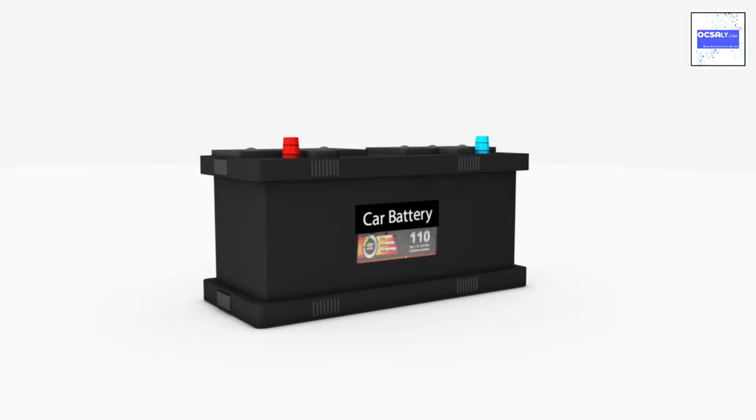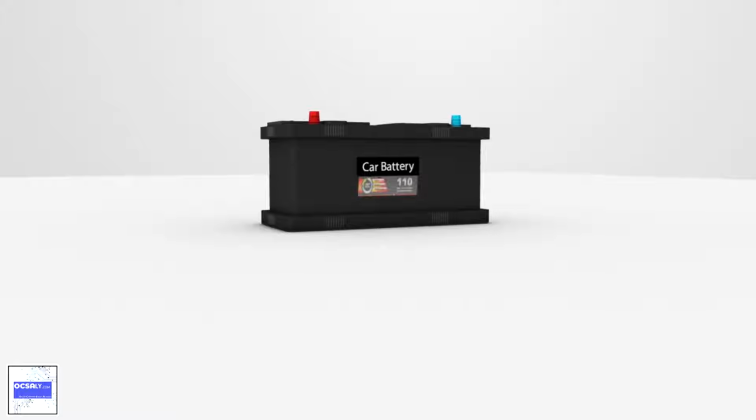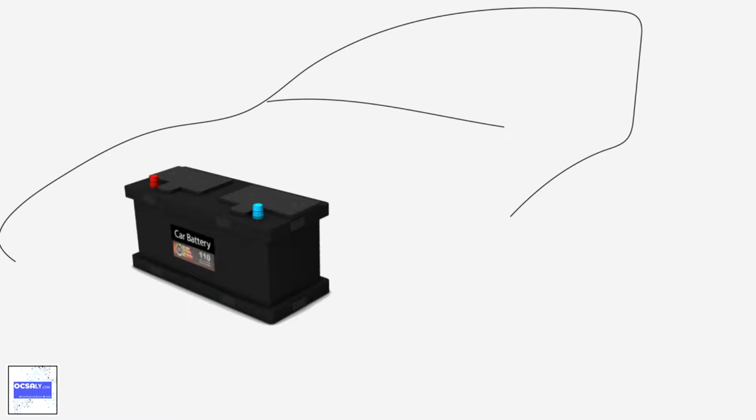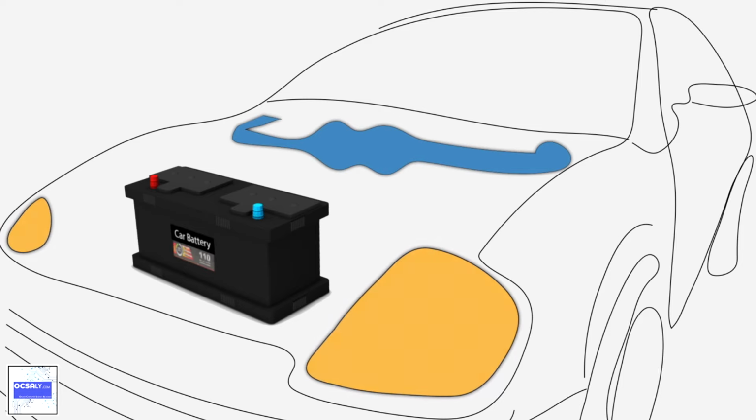Near the fully charged state, some hydrogen and oxygen may be lost as gas from the battery vent. Some water can also be lost by vaporization in hot weather. With older batteries, this meant that battery electrolyte needed regular inspection and topping up. Only water is lost from the battery, and therefore only water should be used for topping up. Any contaminants will affect the chemical reaction in the battery and therefore the performance.